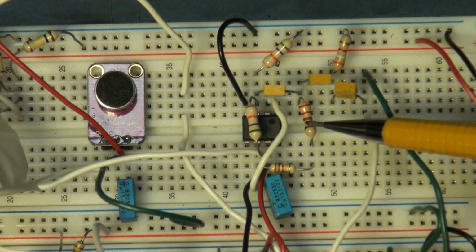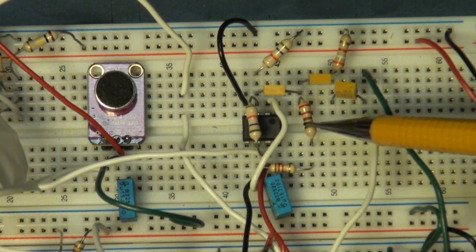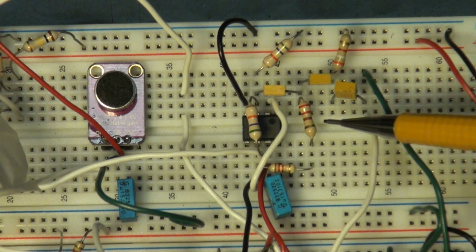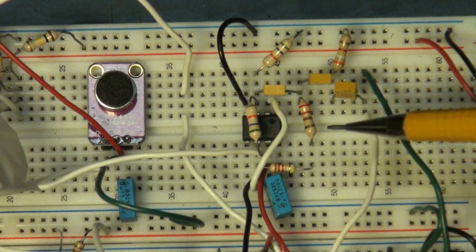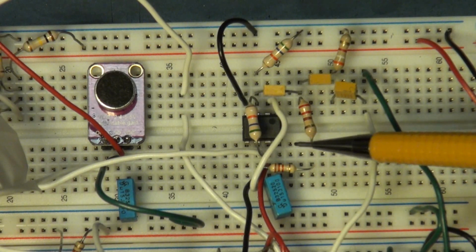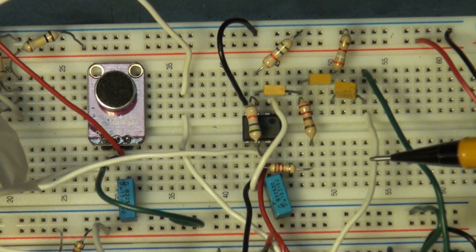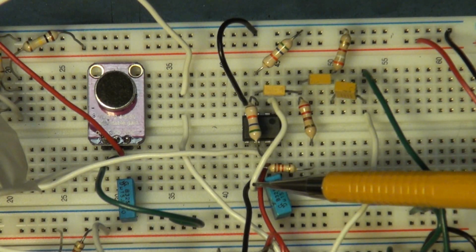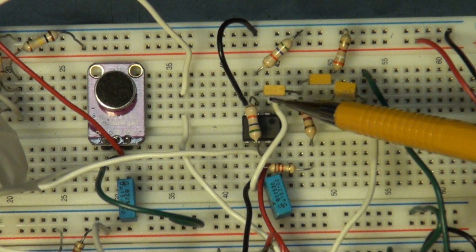And these two resistors comprise the ones that are daisy chained, 1.2K and the 220 ohm resistor, maybe not necessarily in that order, but here they are, going from the junction of C2 to C3 to pin 6 output of the op-amp. And the negative feedback loop is taken from pin 6 back to pin 2 by this jumper wire right here.